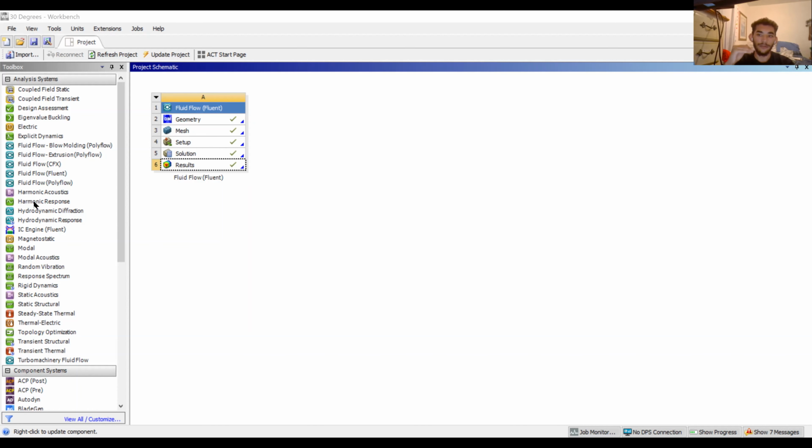As you lower the reduction factor, the more vectors are generated. So we'll just keep it at 3 because 3 is good enough for what we want, and you'll see in a moment. We're going to hit apply, and then this is what we're going to see. Zoom out so we can see. Essentially, these are our velocity vectors. Very similar to what we saw with our velocity contours, but now we can specifically zoom in.